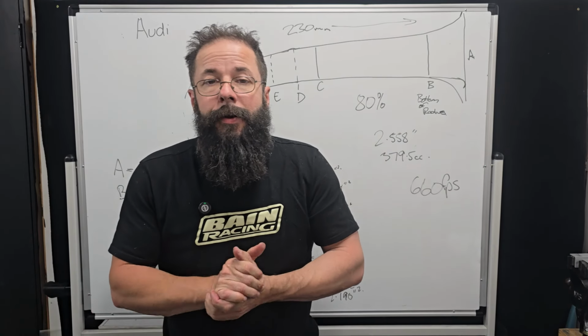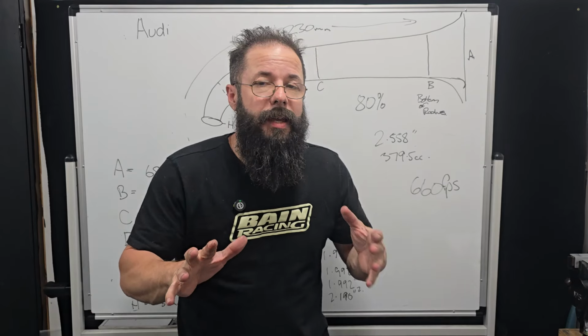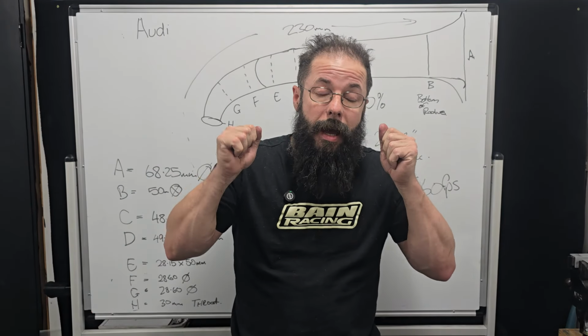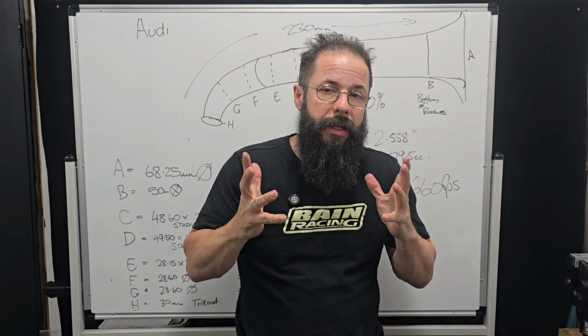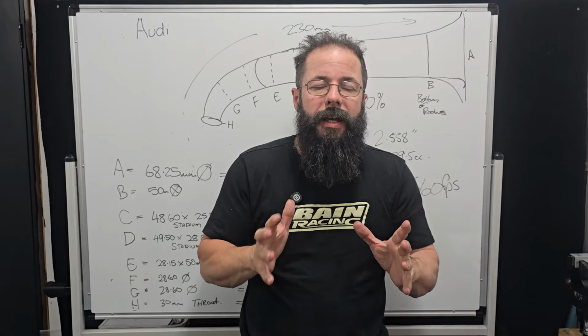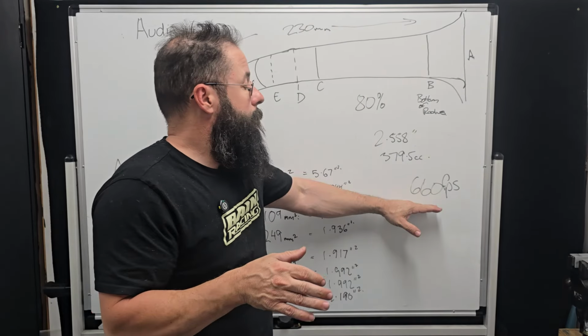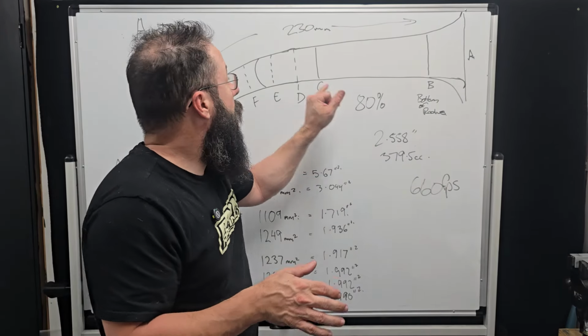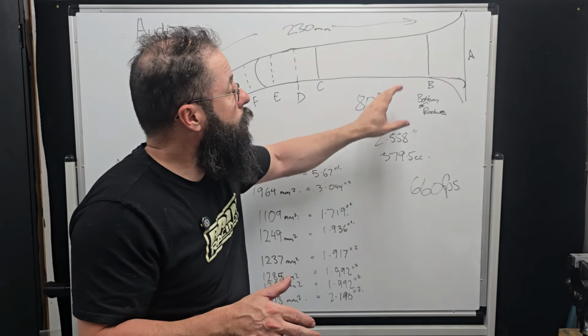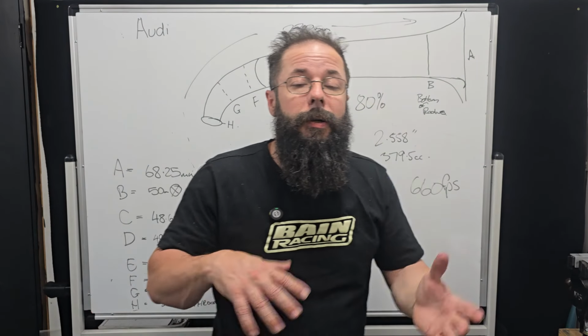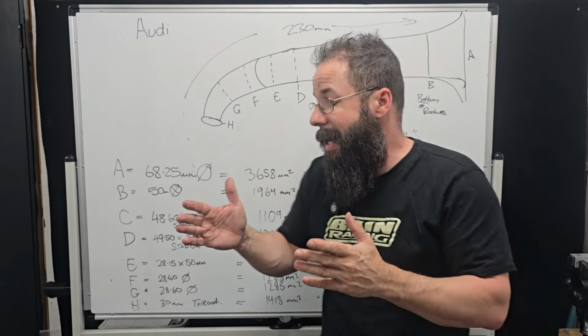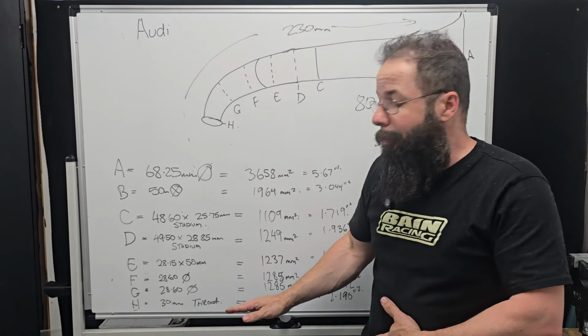So, all right, guys. This is a great example of why I absolutely insist on porting to CSA. We know the whole story of this engine now. We know our velocity is too high in the manifold, but also it's too big at the entrance. So our averages are going to come out not too bad. And we also know where we need to port.